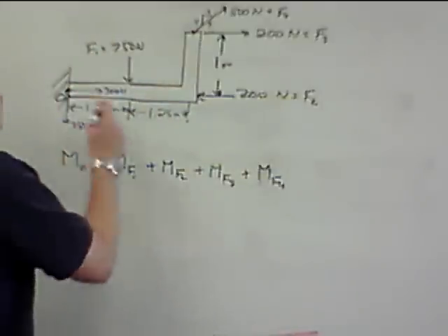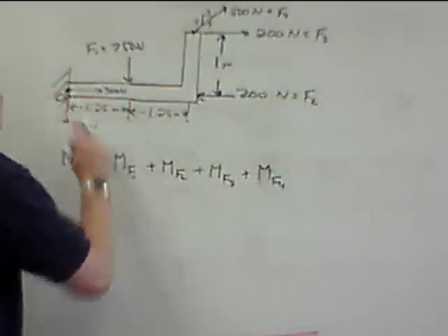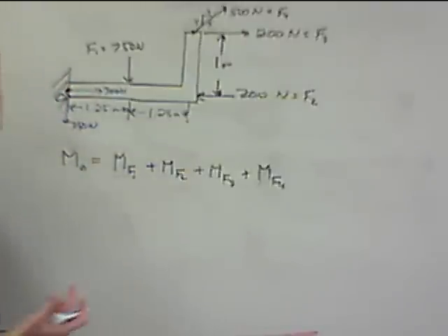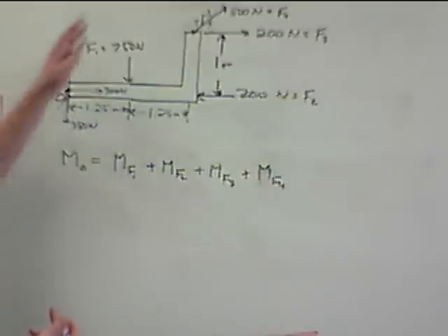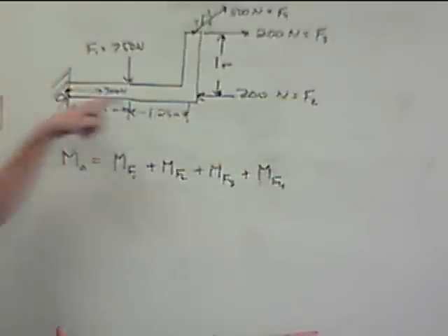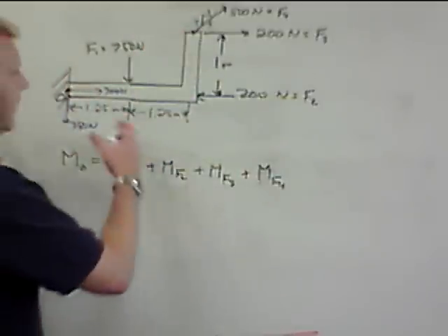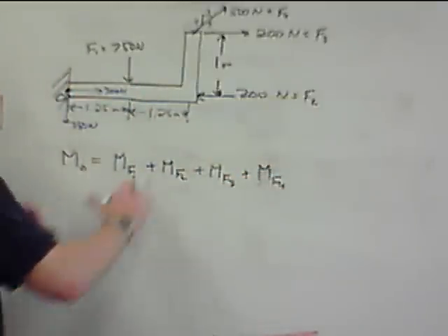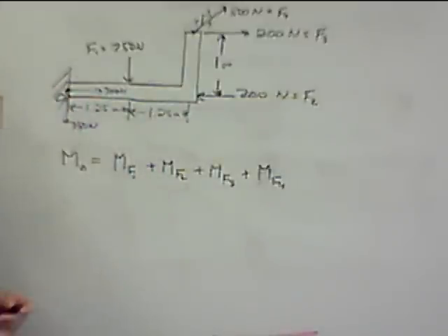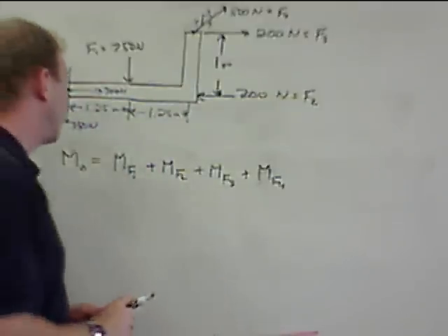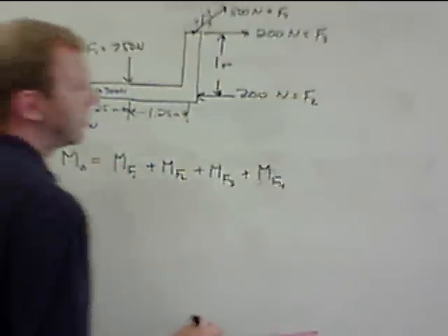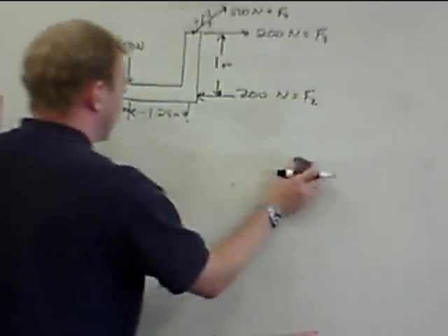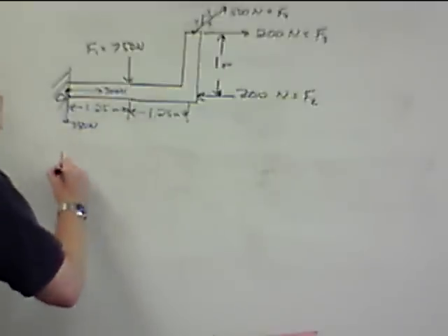All right, start calculating moment. This is all moment about point O. It does matter when you start calculating moment where the equivalent force gets placed. Notice when we added up all the forces, it didn't matter where point O was. It's just going to be a net 300 Newton force to the right, 350 Newton force downward. But when we start dealing with how it's getting twisted, point O's location starts to matter. We'll do these individually first, and come back to the addition at the end.